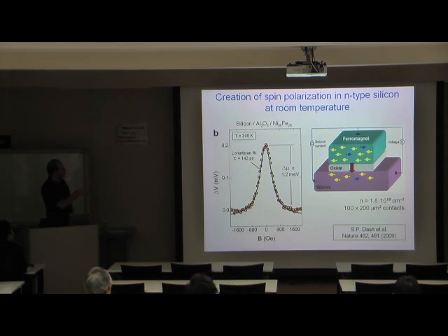This was done for silicon, aluminum oxide, nickel iron structures at room temperature, with the silicon having a doping concentration in the 10^19 per cubic centimeter range. The measurement was done in the so-called three-terminal geometry, where we inject spins from this ferromagnet into the silicon using this current contact and measure the resulting voltage across the tunnel junction by this pair of contacts.